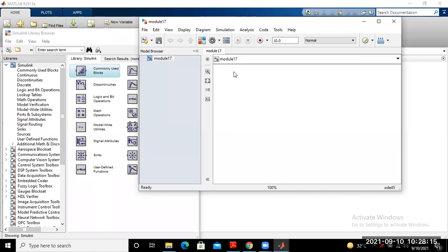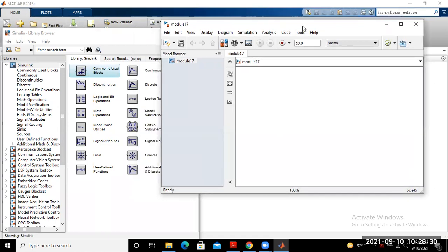Now you can simulate the single phase full wave uncontrolled rectifier for the resistive load. You have to remember what components we require to design this circuit. Whatever components are required, we go to the Simulink library and drag that component into the new workspace.